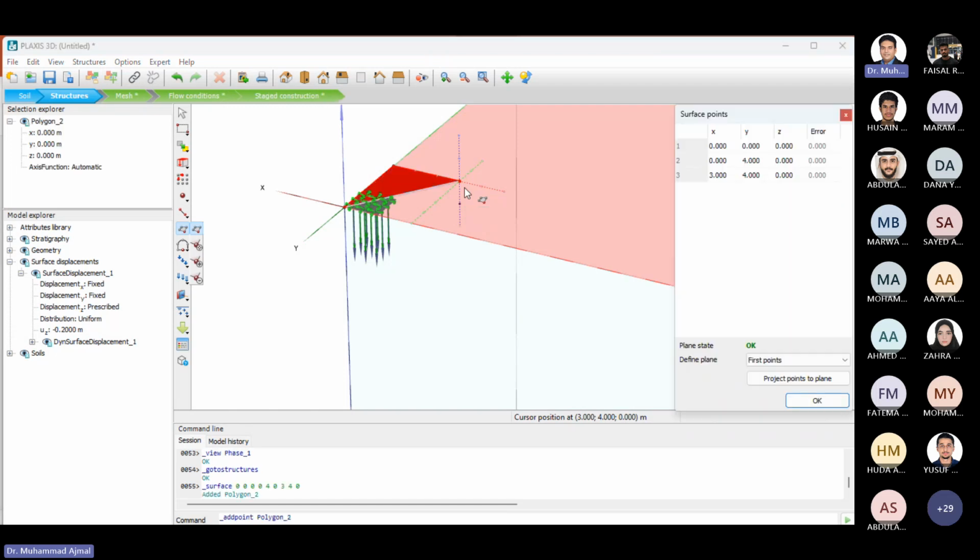Now, when I do that, I'm just choosing random numbers. But in reality, my numbers are not these. So what you can do, you can go to the right side of the screen and put your four nodes, because for a rectangular surface, you need 4 points. So you can come here and edit your points according to the size of the foundation.